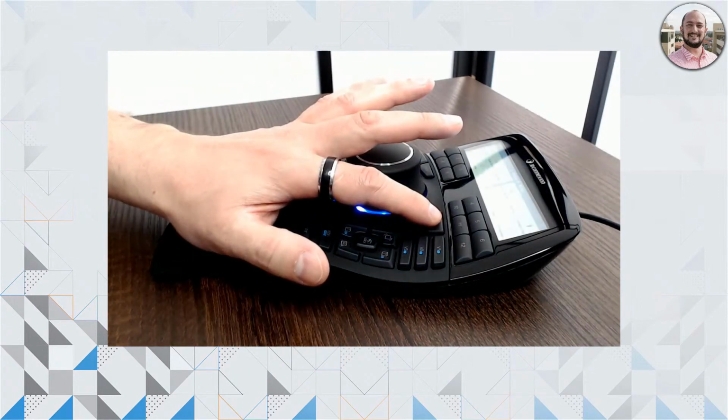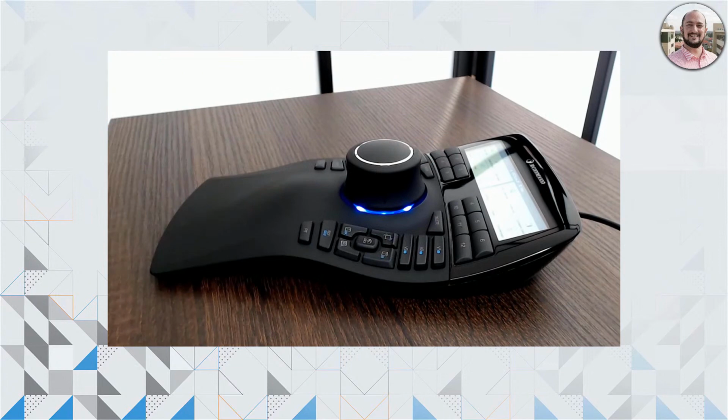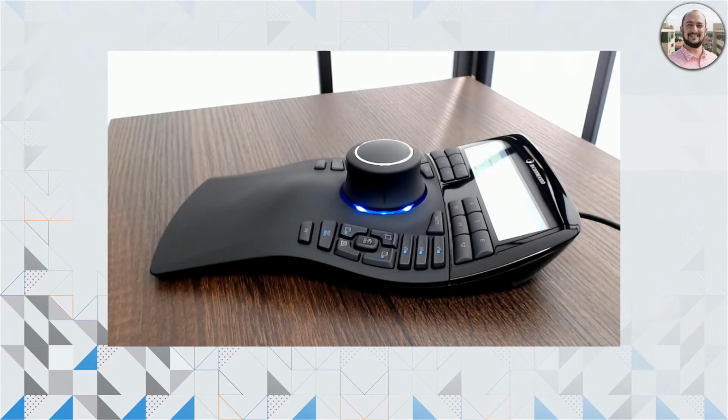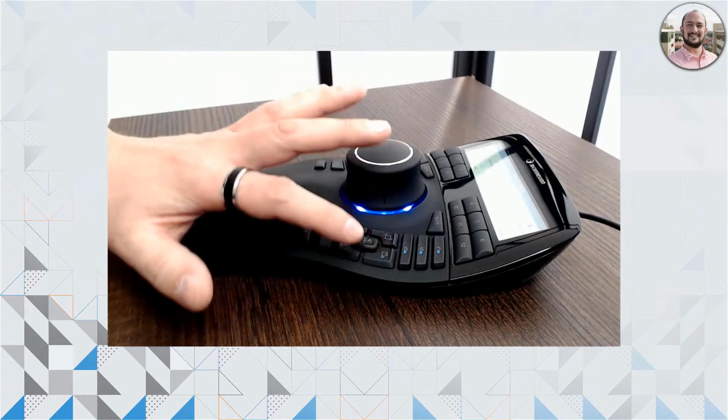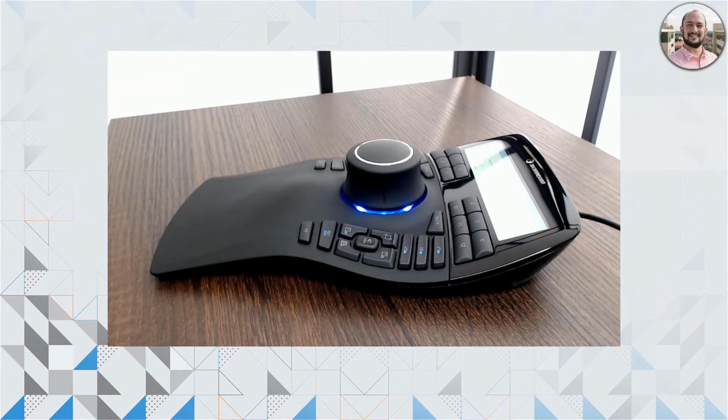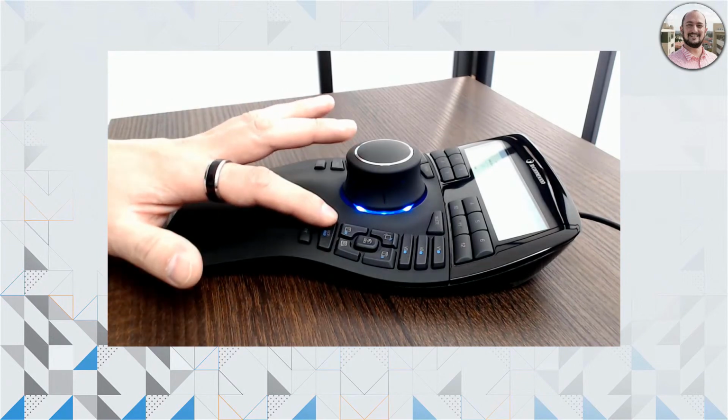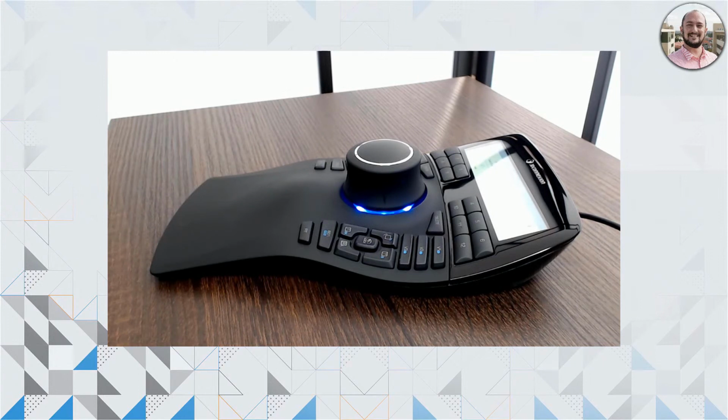On the right hand side you can find a delete button. There are 3 dedicated buttons for quick saving and recalling 3D views. There are dedicated buttons for all sorts of specific isometric views like the top view, the front view, all sorts of side views. And also you can find the isometric view button, which helps you quickly going into an isometric or axonometric view once you are in a 3D perspective view perhaps. And also here at the bottom you can find the fit screen button, which helps you quickly finding the whole model. If you are zoomed into some place of your model and you push this fit screen, then the software will quickly show you the whole model.